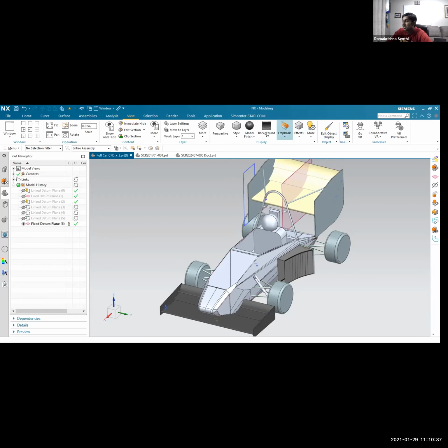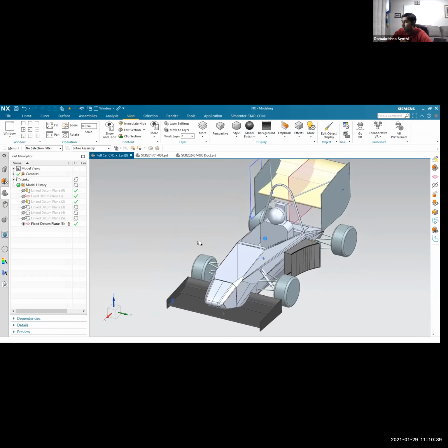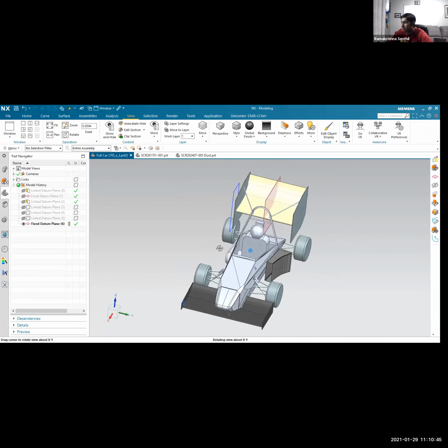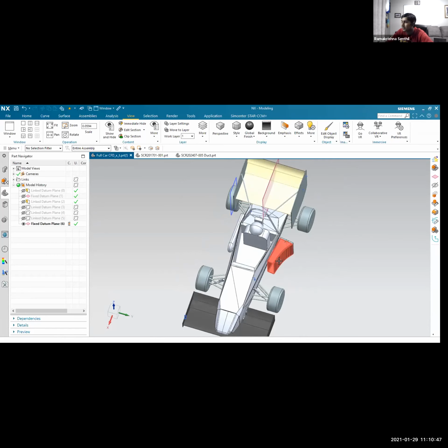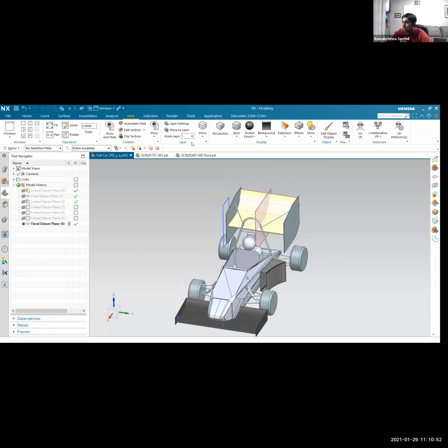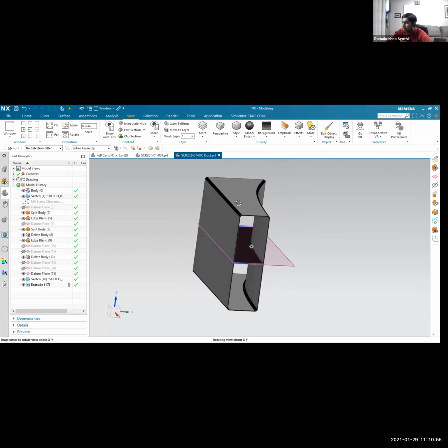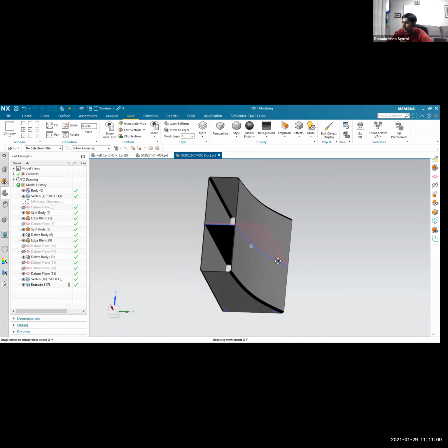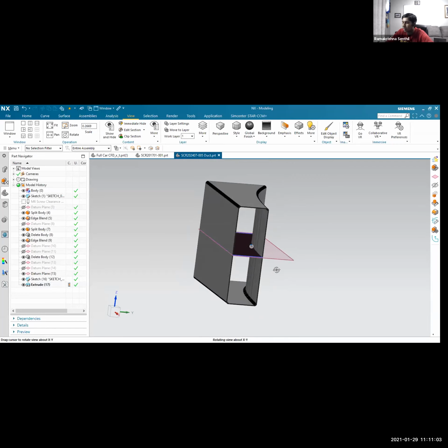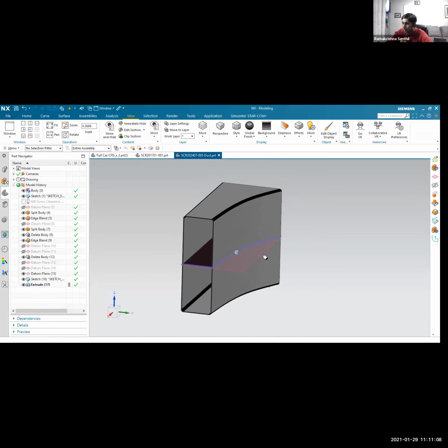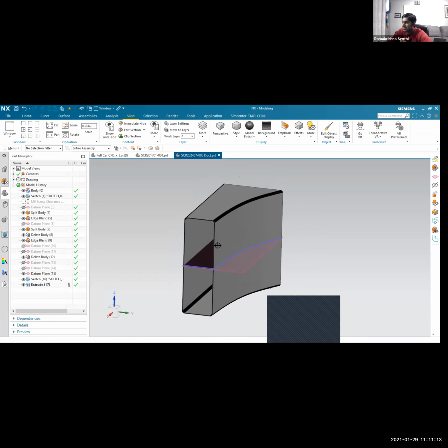Anyways, I wanted to show you guys how to replace a part in STAR itself, which makes things a little bit easier. What we're going to do is import this car, and then replace the duct with this duct, which has a flat plate in the middle, hopefully, which can help with flow separation. We'll find out if it really does by the end of the simulation. I haven't tested it yet, so I don't actually know.